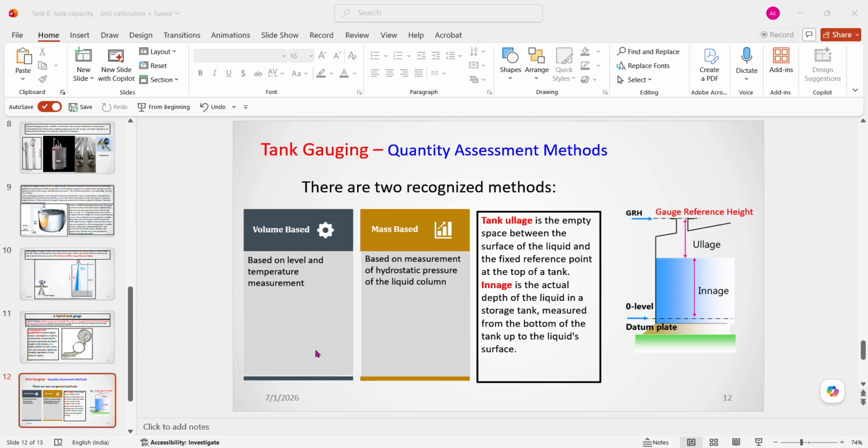It is tied to the indicator, and the indicator will give you a signal of how much level is there inside the tank. This is the tube level gauge. This is mounted on the tank itself at the bottom. One is at the top, and the liquid will flow through this from the bottom, and it will give you the actual level, because water maintains equal levels. So this will give you the actual level. Whatever level you are seeing in the tube, that is the level of the tank.